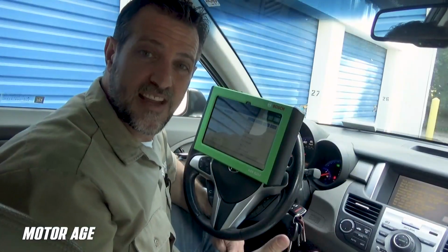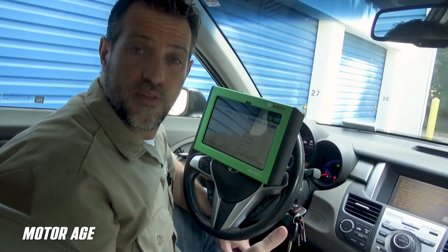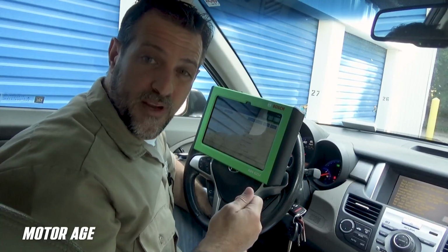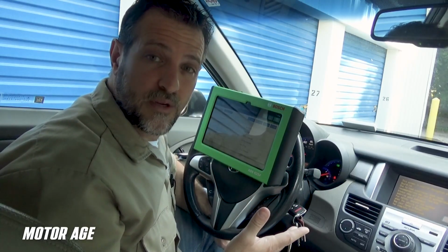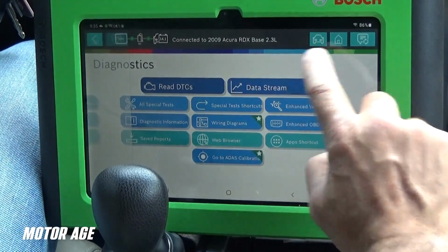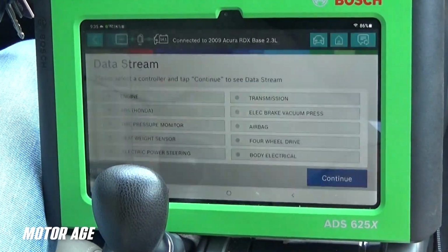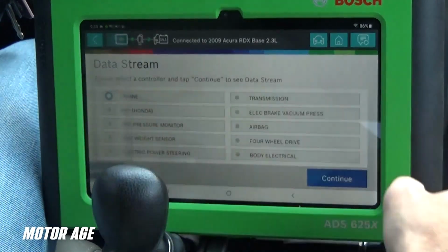We are now going to complete our repair and repeat the same test we performed earlier to infer that the repair solved the root cause fault. We're going to simply capture the same data we looked at before to infer that the system is now working, both the command from the PCM and the signal change from the feedback switch. We'll go back into our data stream again and select the information we found pertinent.